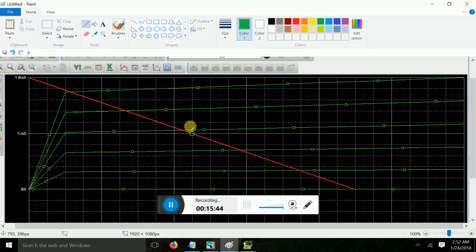Once VCE goes down for the negative half cycle of the 5 volt amplitude output, and it goes to 9.5 for the positive half cycle, it means VCE is going to the saturation region for the negative half cycle, because it is at 4.5, and going out of 9 for the positive half cycle because it is coming to 9.5. That's why the distortion is coming.